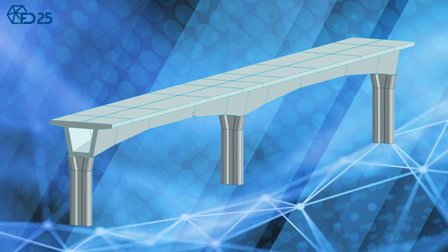There's a question: is it possible to do code check even for a double L section with the gap? Yes, it's possible, but you have to understand that it treats this double L section as if they are welded together. So if you calculate the bending stiffness in cross direction, there will be a really lot of weld between those two L sections, so there's a shear interaction between those. But if you take that into account in the designs, you put some flat bars to connect them, then it's fine. Then you can do design like buckling check and lateral torsional buckling check and warping and everything.